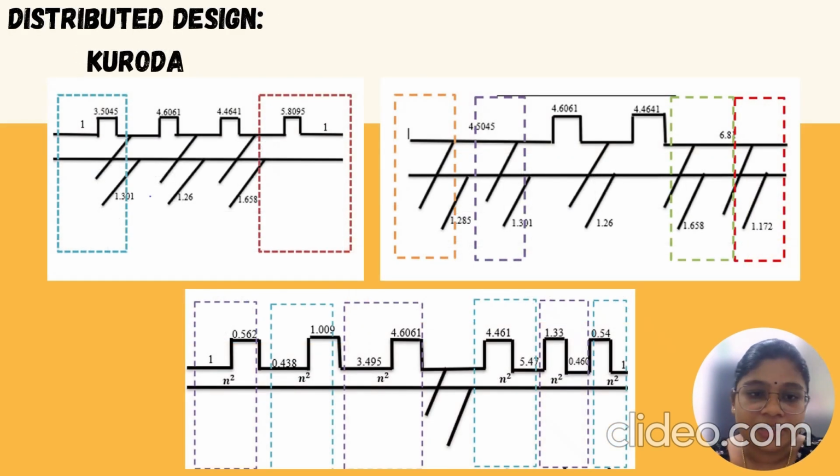Okay, the first schematic shows the initial Richards transform filter with open and short circuit stubs arranged as a derived layer. So the box section and eyelet section are difficult to realize directly. So I changed the short circuit to open circuit, and the last one is also the same, the highlighted box which is a short circuit, I changed to open circuit. So this is the result of how the short circuit became open circuit.